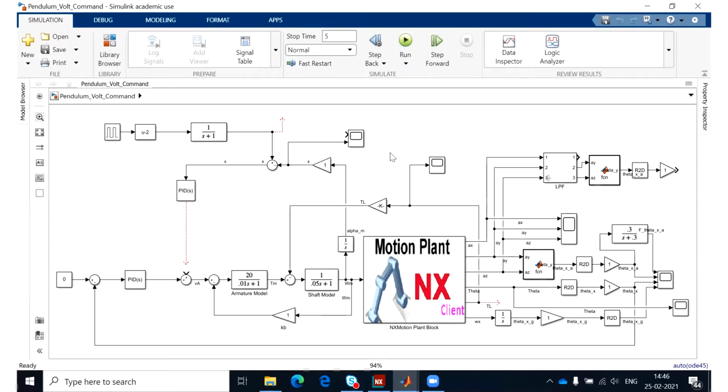Before I do the simulation, you know that this is the angular velocity of the motor, as I said. If you integrate that, what you get here is the angle of the motor shaft. I have named that alpha m, even though in the lecture in the control course we had theta m, but because we have used theta for the angle of pendulum, I use alpha for the angle of shaft.